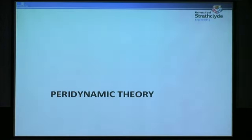And these equations, as you will see, don't include any type of derivatives. So it means that, if you think about fracture and cracks, we have discontinuities. In this particular formulation, since we don't have any derivatives, our equations are always valid. And also in our equations, as you will see, we are using very simple crack laws, which is much simpler than what people are using to predict damage.